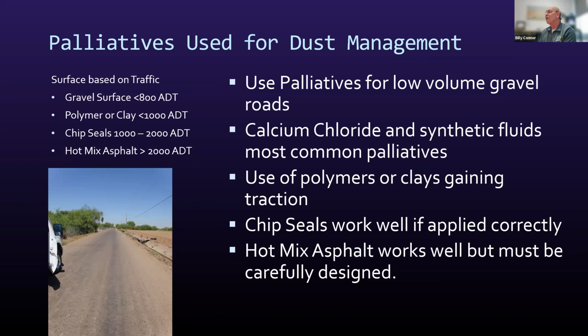Calcium chloride and synthetic fluids in Alaska tend to be the most prevalent palliatives that we're using, although there are others such as lignin sulfonate, which can work pretty well. And water is always a good one.